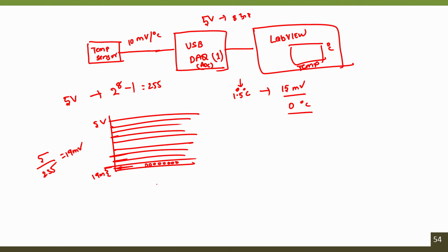Even by utilizing an 8-bit ADC, by slightly changing the gain, by introducing a signal conditioning circuit with a gain between the temperature sensor and the ADC, the temperature can be displayed with a very high resolution.